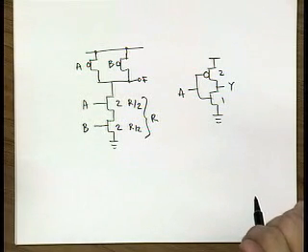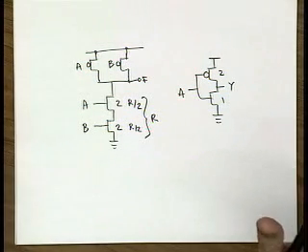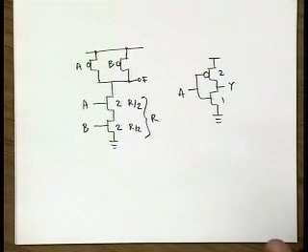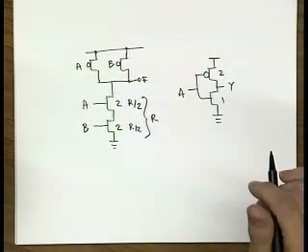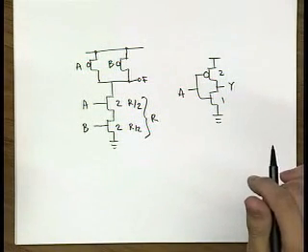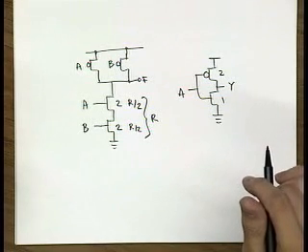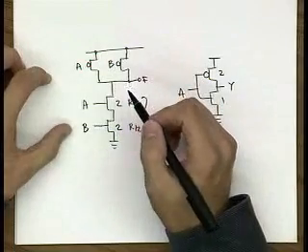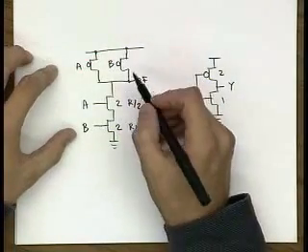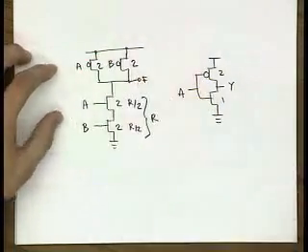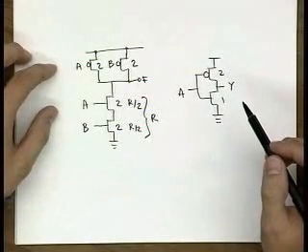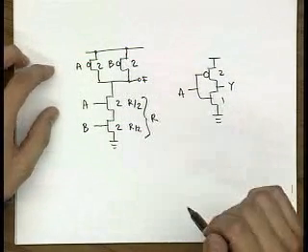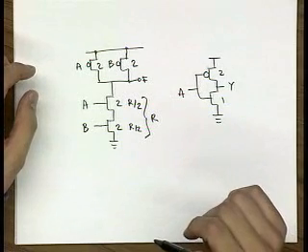That's the best case, right? You want to size your transistor such that you're sure that your delay is going to be a certain number under worst case conditions. Make it as big as the inverter, right? Because that's the same pull-up resistance.